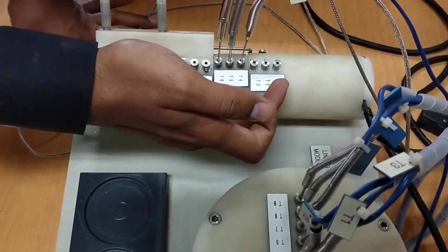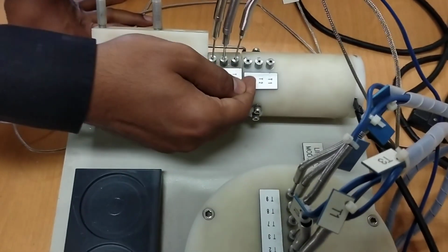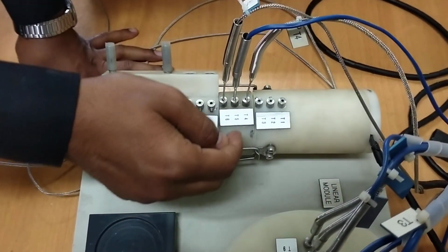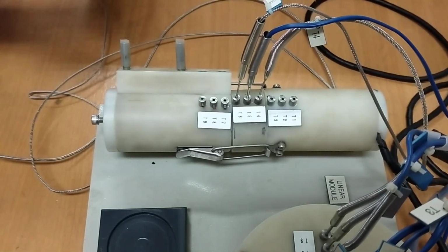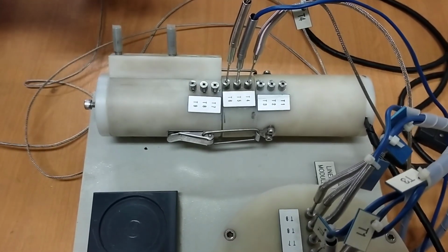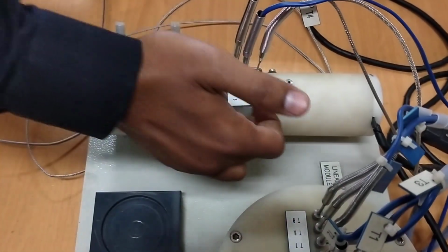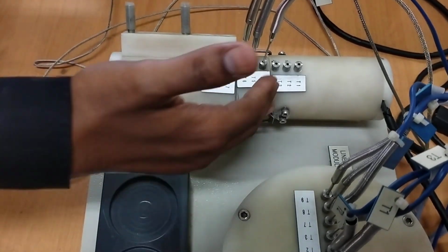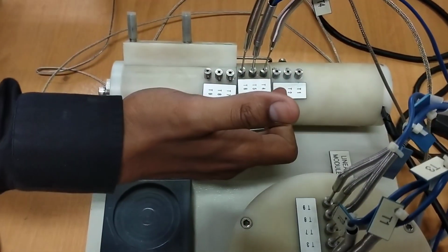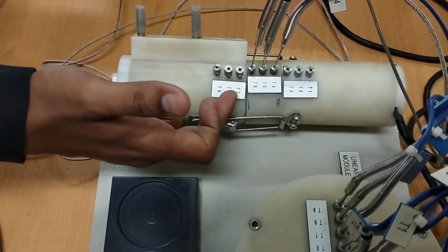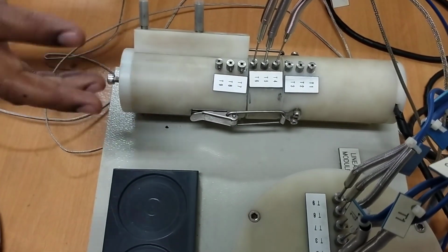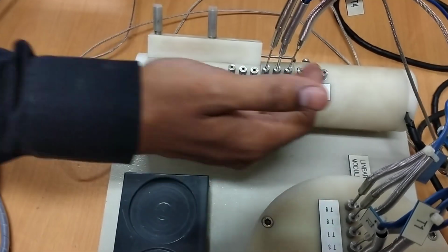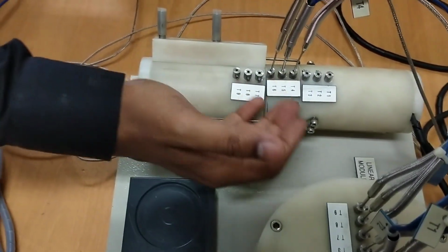You can either use T1 and T3, but don't use T3 and T4, because there is a contact between the two surfaces. Since the contacts are not perfect due to air gaps, there exists a thermal contact resistance between these two. So you will observe a certain temperature jump between T3 and T4 and between T6 and T7, showing that there are air gaps. To avoid that, we must tighten it as much as we can.